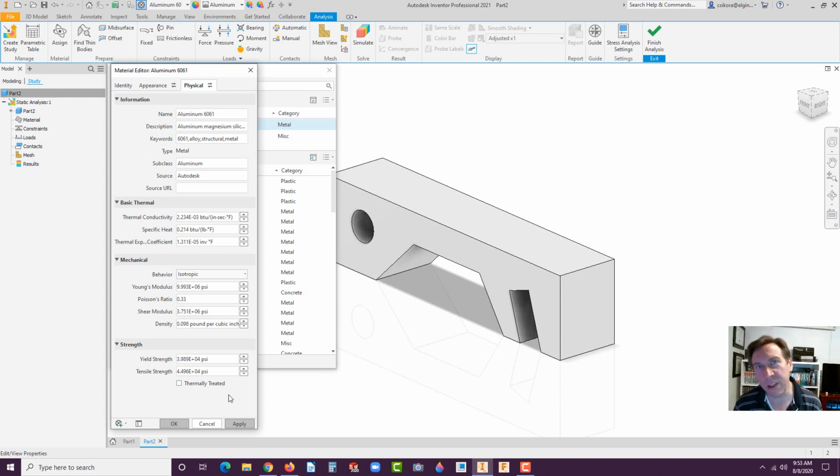Now, when I give you those limits and you look those up for megapascals or PSI, essentially we're talking about yield. Yield doesn't mean it's actually breaking or rupturing. It's typically an indicator that you've bent something beyond its limit of flexibility, what they call the elastic limit, and you've gone into what they call the plastic range. And once it's in the plastic range, it's not bending back. So we refer to that as failure if it doesn't bend back.